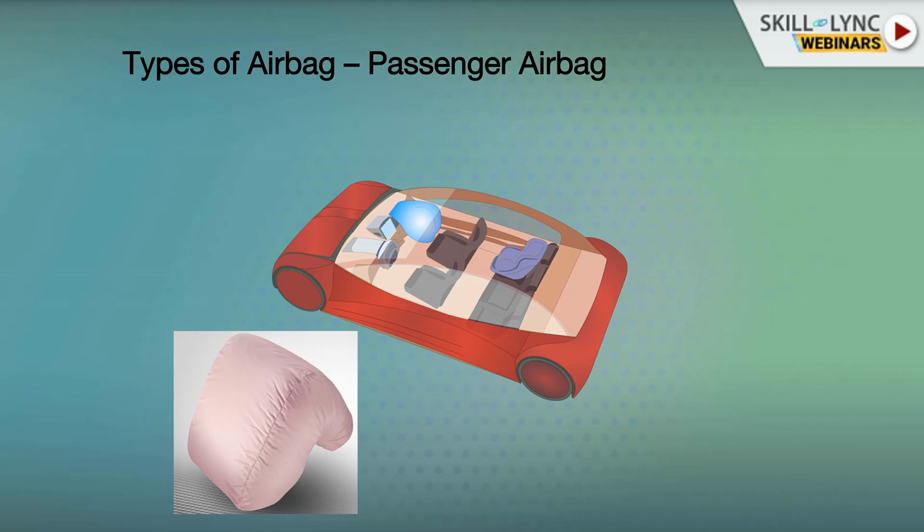At the particular IP region, there will be a weaker section inside. It is designed so that the weaker section will tear off, assisting the airbag to come out. Those parts are getting clubbed, due to cost effectiveness and the aesthetic feature that is being developed. This passenger airbag is roughly around 120 to 150 liters.